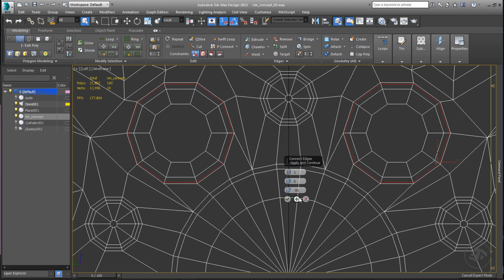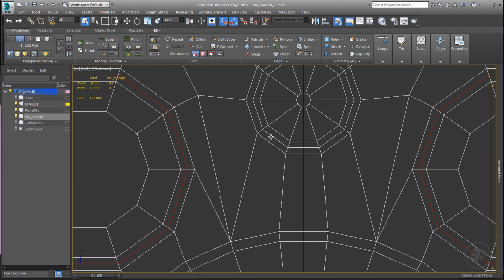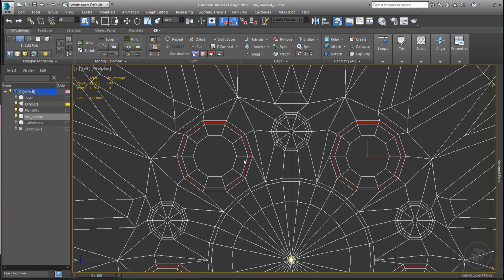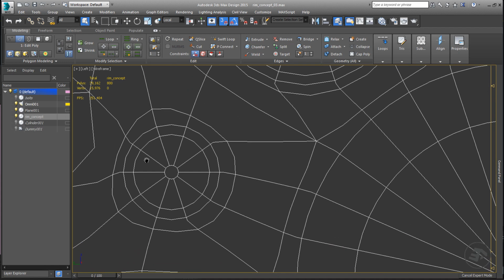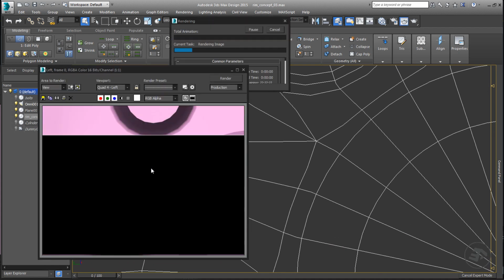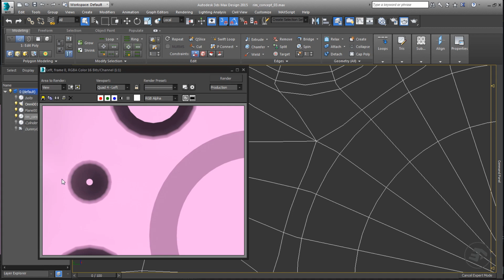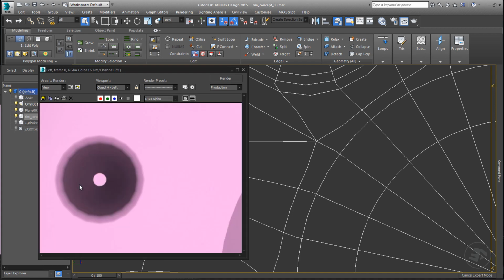The outside supportive loops will be consumed by the Turbosmooth modifier, while the inside loops will remain in their places. And keep balanced tension around the edge loops of the holes, thus controlling the gradient color effect, or to be precise, the light effect over the surface.